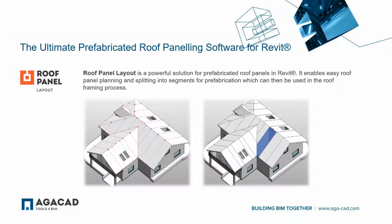Panel layout is a powerful solution for prefabricated roof panels in Revit. It enables easy roof panel planning and splitting into segments for prefabrication, which can then be used in the roof framing process. It automatically generates a panel layout plan for any architectural roof. It uses predefined rules to draw symbolic lines indicating the future panels, and then creates real Revit roof panels. These roof panels can later be framed using wood or metal roof panel frame. Prefabricated roof framing can include rafters, battens, valley joists, roof boards, and so on.